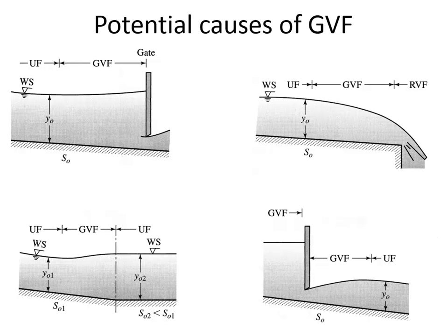But here, we've got supercritical flow, but that's just fine because the slope is steep here. And so you'll notice this looks like it's pretty steep just compared to some of the other slopes. And it's gradually varying flow because here it's supercritical, and then it gets to the normal depth, and it's still supercritical. You can have supercritical flow and it be uniform. There is such a thing as uniform supercritical flow.